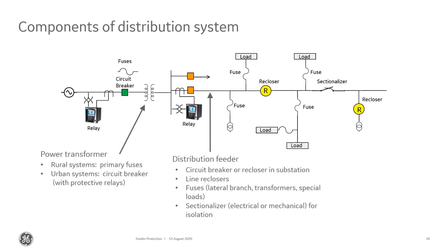Whereas if we stuck that middle recloser in there, if there's a fault out on the right of that feeder, that recloser can open to isolate that fault and maintain the loads between that breaker and the other recloser.